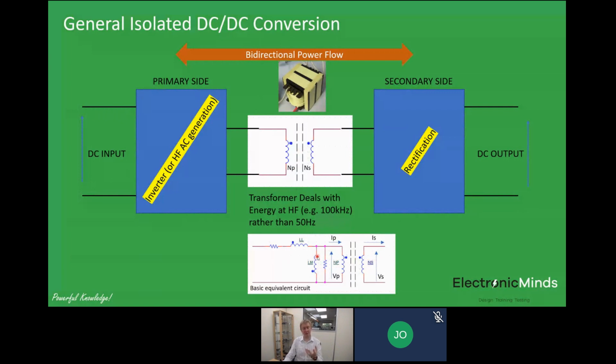And that's just the fact that we've got a number of turns of wire wound onto a magnetic core, which gives us inductance. And that's the magnetizing inductance of that particular device. We've also, in parallel with that, got some resistance, and that's to model the core loss. So we're moving the core material through its BH curve. That incurs loss every time you do that, so we can model that with this resistor.